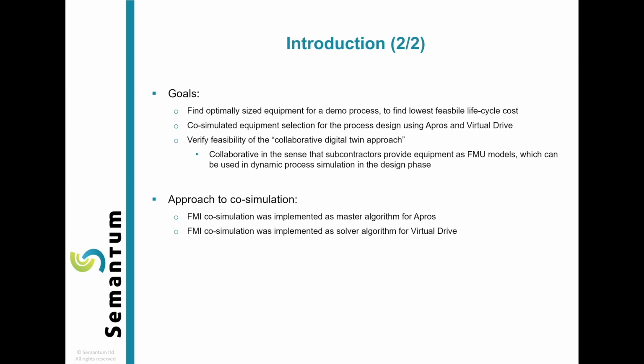And here, the collaborative part means that we have different subcontractors providing their equipment as FMU models during the design phase, which we can then use to find the optimal size of their equipment in the whole process by dynamic simulation. And our approach in this case was FMI co-simulation. So we implemented the master algorithm for Apros and the solver algorithm or slave algorithm for Virtual Drive.